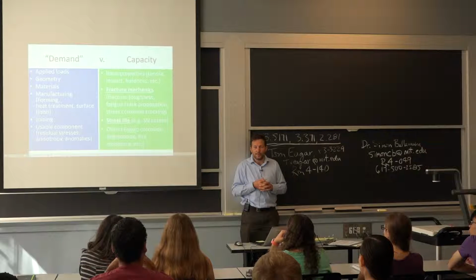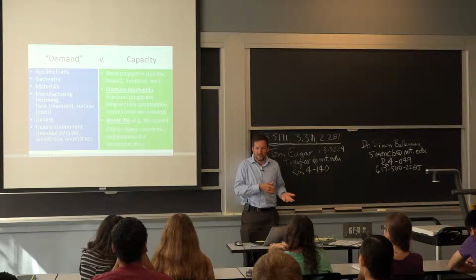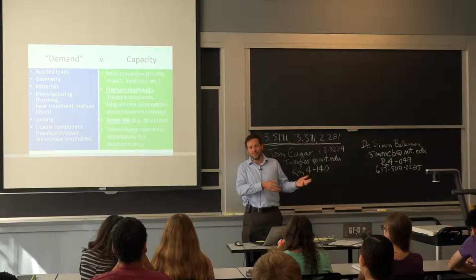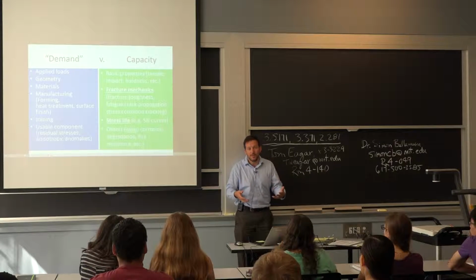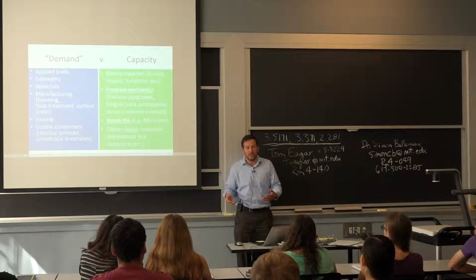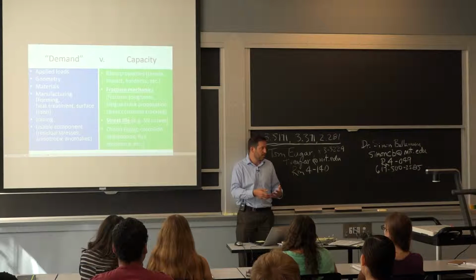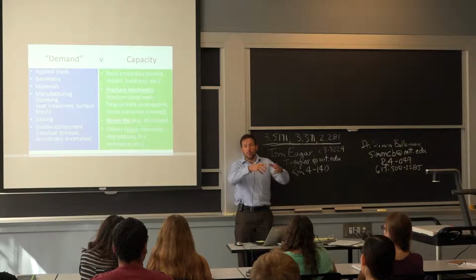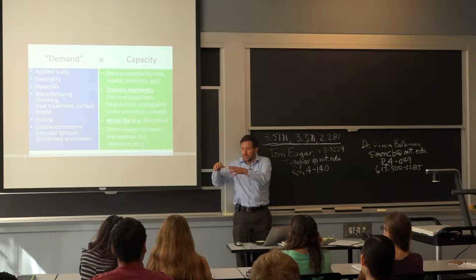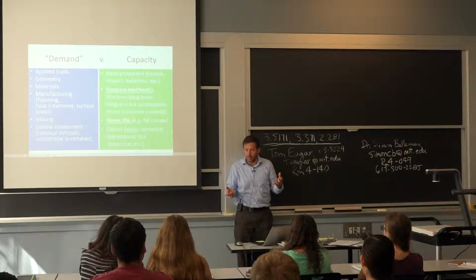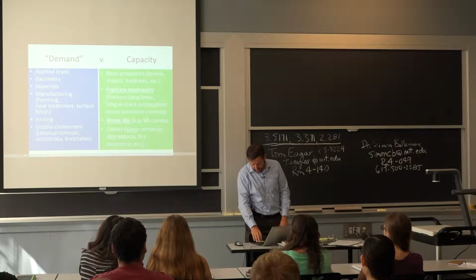So this, in the past, helped me a lot trying to analyze a situation. When we're talking about a real problem, like Professor Eager said, you don't have 4 pieces of information and you try to put it together. You have to look for the information. So when you go and look for the information in general, if you had a failure or if you're designing something, you want to know what is going to be the applied condition, what is going to be the demand, and then given how I'm going to build it, how strong is that material going to be? And you want a certain ratio between them, and we talk about a factor of safety then.